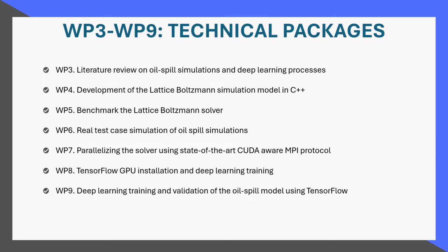First, in WP3, we conducted a literature review on oil spill simulations and deep learning processes. In WP4, we developed the lattice Boltzmann MRT LES oil spill simulation in C++ software programming. In WP5, we benchmarked the lattice Boltzmann solver. In WP6, we conducted a real test case simulation of an oil spill. In WP7, we parallelized the solver using the state-of-the-art CUDA-aware MPI protocol. In WP8, we used TensorFlow GPU installation and deep learning training to train a model.